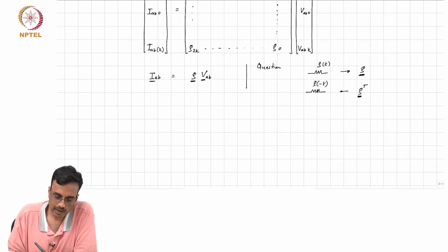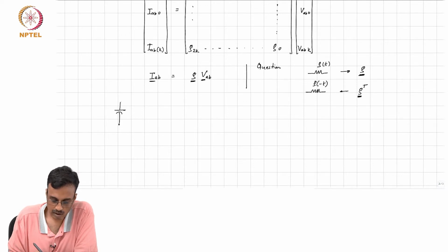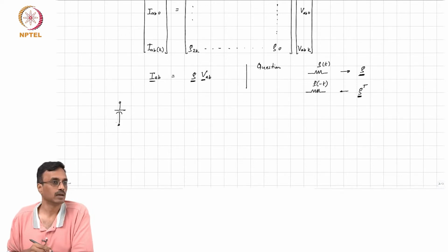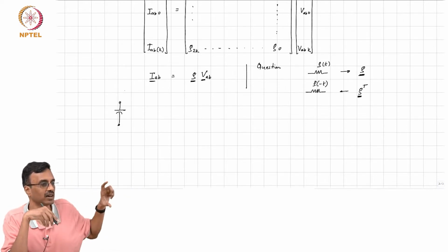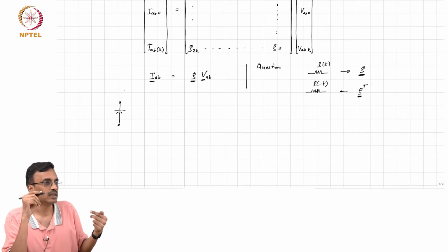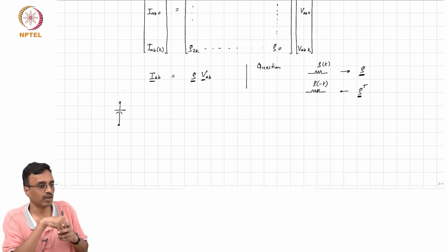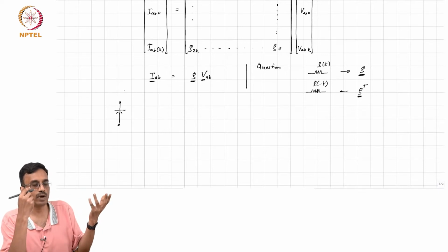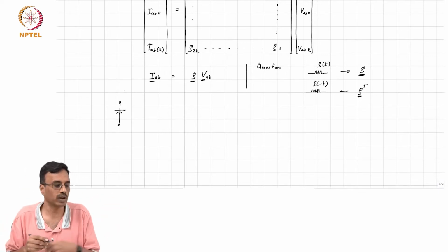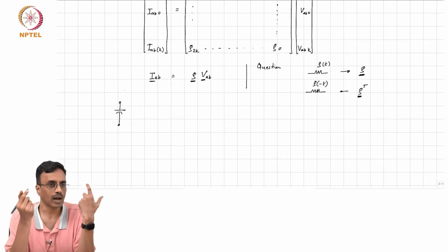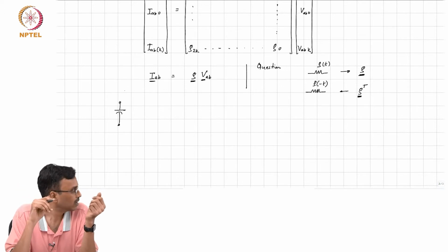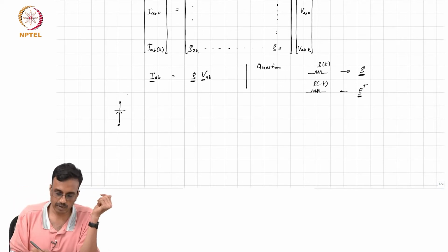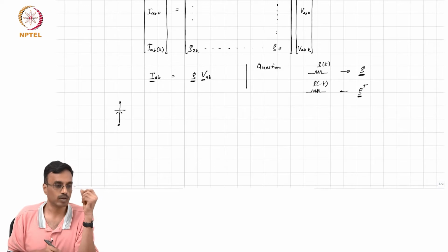So, we have conductances and capacitors. This is a linear capacitor, right? Just because this capacitor is linear doesn't mean the current through it has only a single frequency component. It's embedded inside a time varying network, so the branch voltage and the branch current will all have these multiple frequencies. If it's linear, let's see how the currents are related to the voltages.